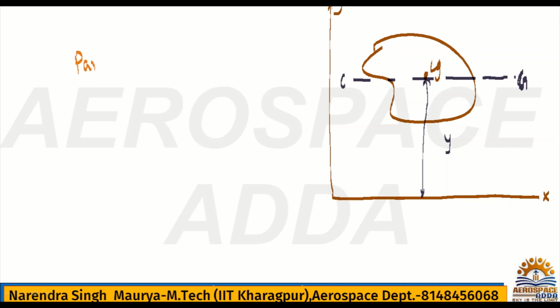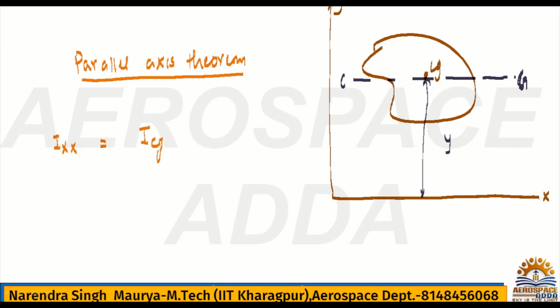Now, what is the parallel axis theorem? Simple. The rotational inertia about any axis is the sum of the second moment of inertia through the CG parallel axis, plus the total area of the body times the square of the distance between the axes. So through the parallel axis theorem, Ixx is equal to the moment of inertia through CG plus the area of this body. Say the area of the body is A, and this perpendicular distance is y square.